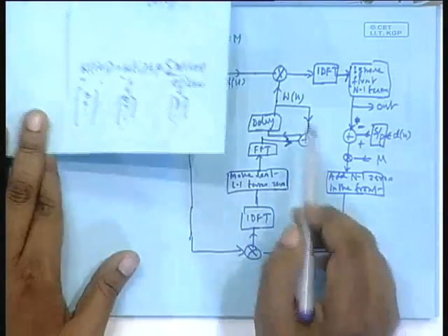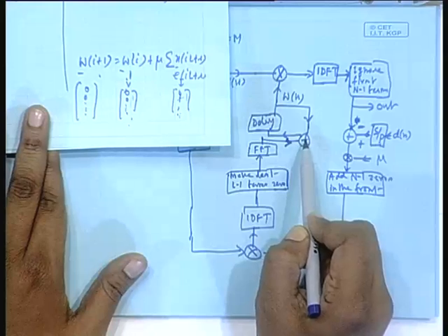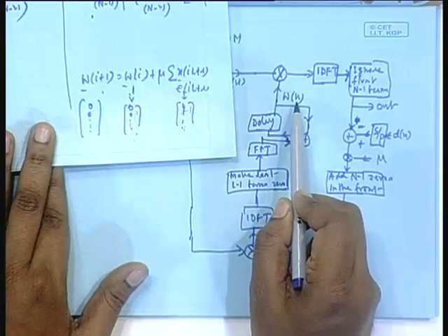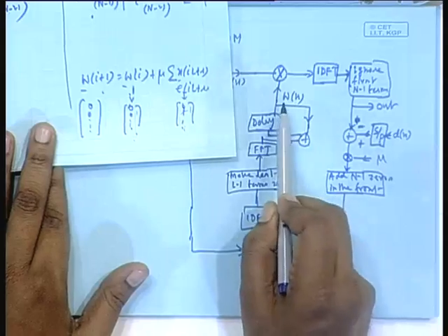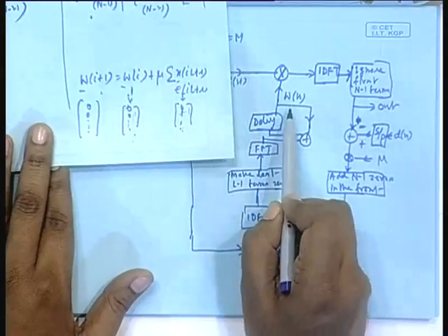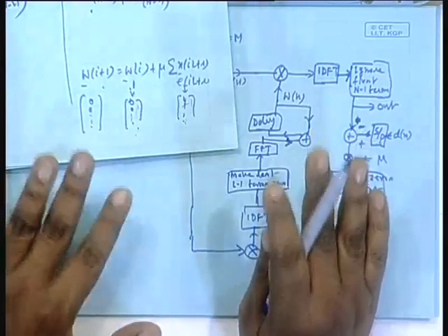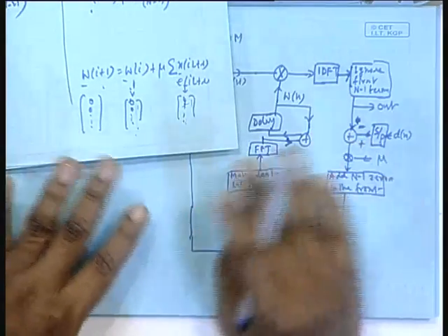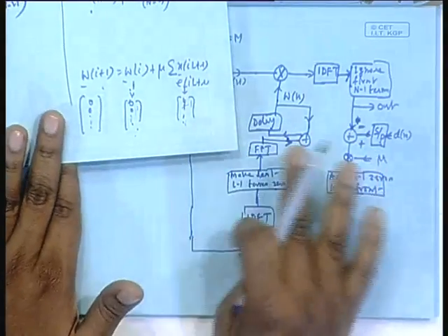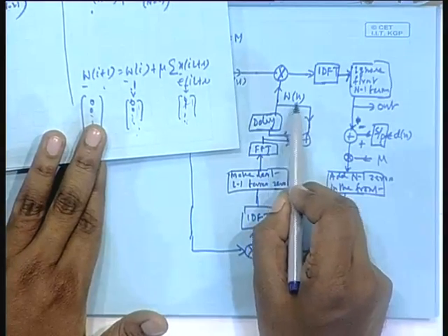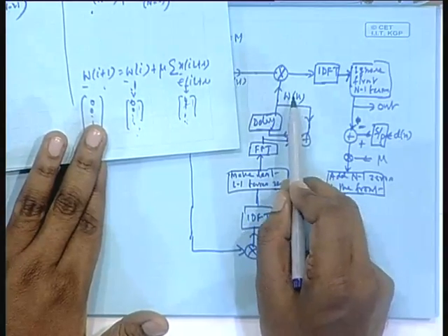What I am doing is the current weight. Mind you, this k is the DFT index k; this W is actually for the ith block, so there should have been an i index here, but in this figure, to avoid complications and so many symbols, I avoided it. Everything here is with respect to the ith block, so k only indicates it is the FFT domain.